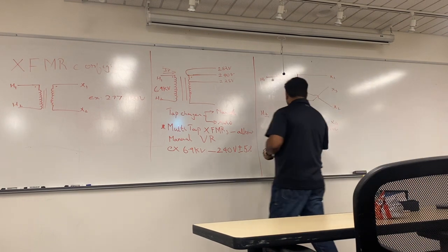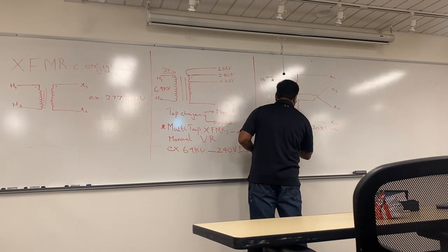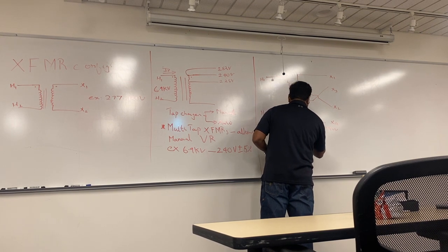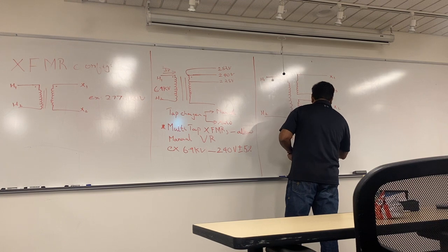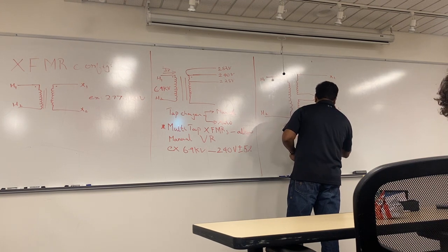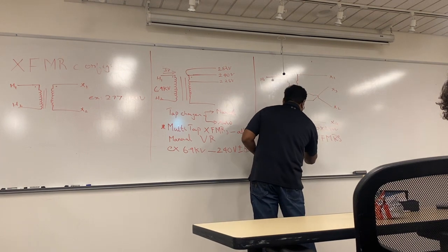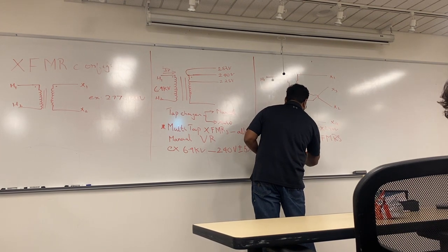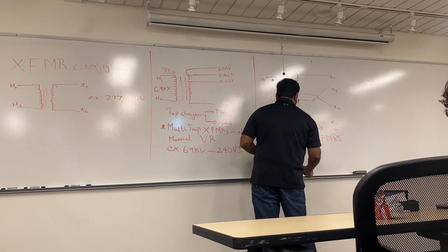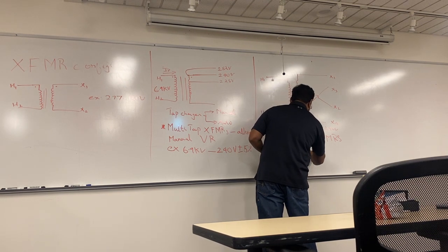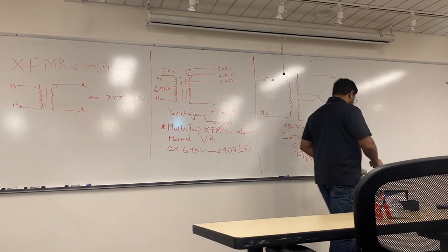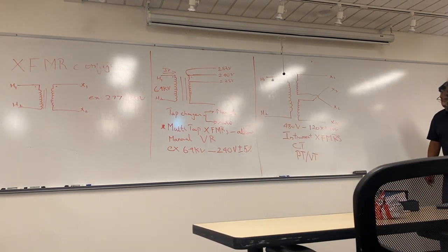It's very common in instrument transformers. Instrument transformers are your CTs and PTs. Sometimes we call them BTs, and I'll tell you what those are. A CT is a current transformer. A PT is a potential transformer. But keep in mind, every now and then you are going to see BT, and every power utility is still debating whether to use a P or a B for it.